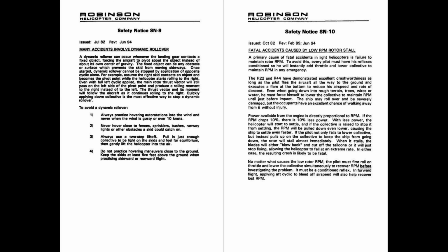While flying with low RPM, what might pushing the cyclic forward do? A forward cyclic will lower the nose, but it will also lower the RPM of the rotor. If the RPM drops too much, it is not recoverable.